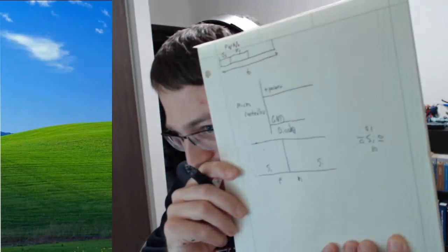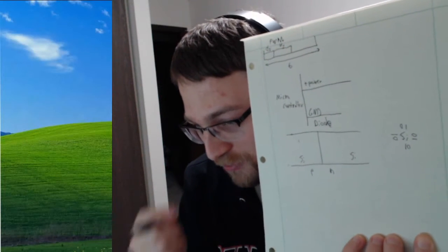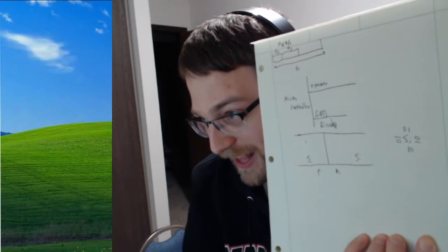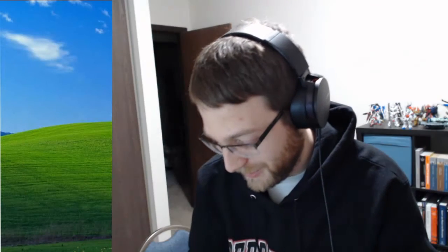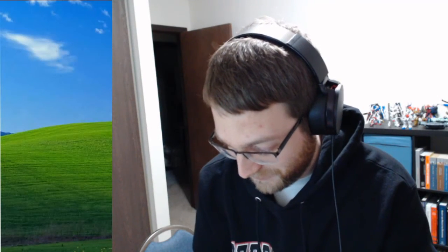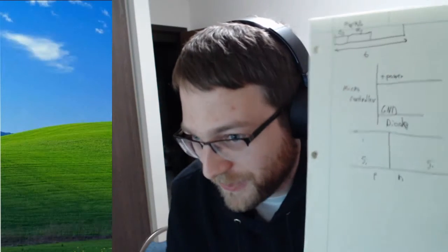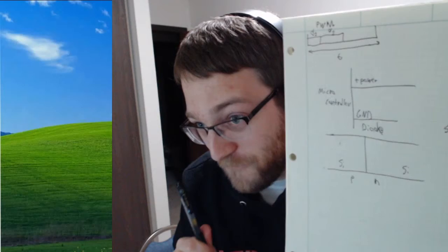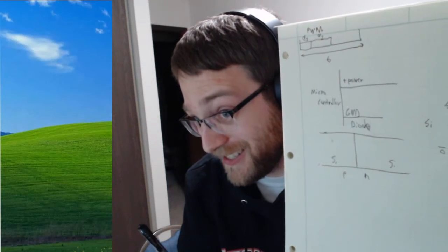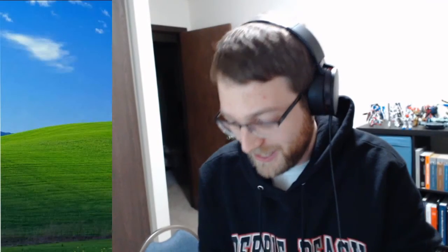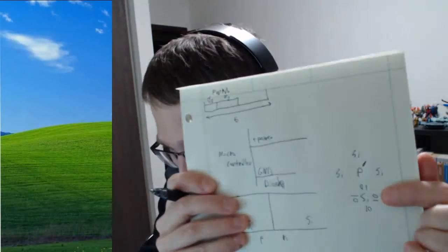So what you start doing is breaking up the crystalline silicon lattice with other elements. You'll have 4 silicon around it, and then you'll introduce something like phosphorus. Phosphorus has 5 valence electrons, so it'll have an extra electron just hanging off right next to it.